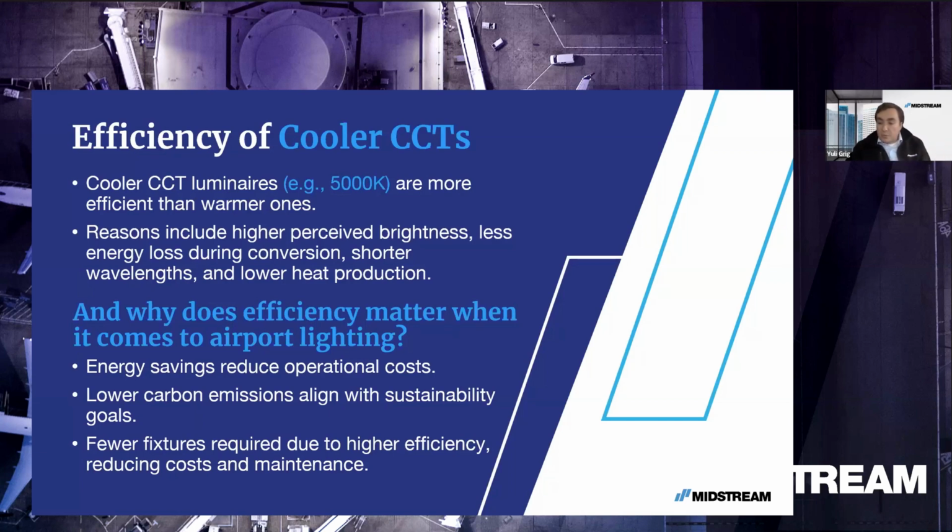So we also have a problem with our sustainability goals, because we're using more than we should be. And then remember that it's not always perfect. If you have a luminaire which is 1,000 watts and there's an array of them, and you just manage to reach 19 lux, then you have to put more luminaires on, and then you will go to 23, 24 lux. So you basically have a little bit too much light and a bit too much energy, but there's no other way to do it, because to get that one extra lux you've had to increase the number of luminaires, because you have less efficiency. If you could only increase the efficiency, you might not need the extra fixtures. So that's why I think overall it's better to have higher efficiency if you can.